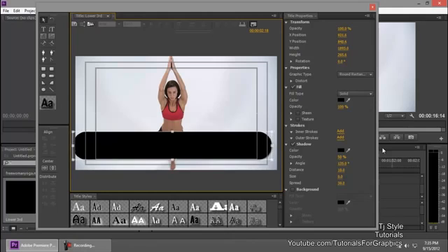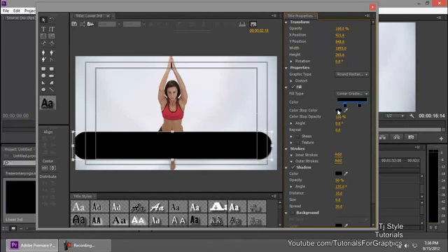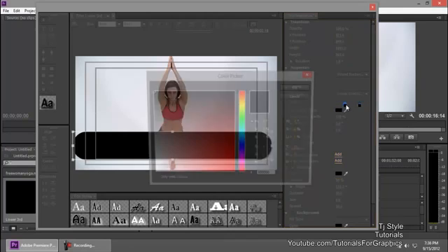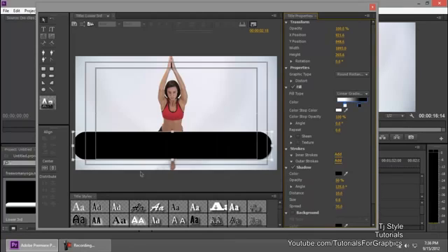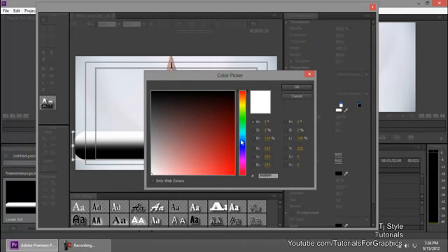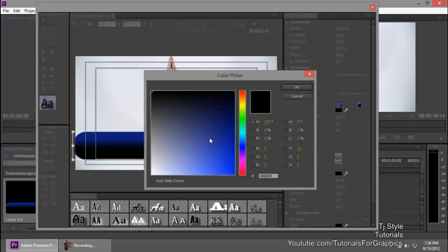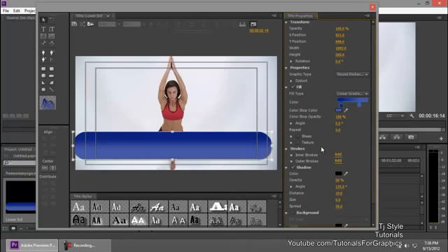And then guys, you of course have the option to change the fill color of this box. In the title properties, go down to this panel, come to Fill Type, and go to Linear Gradient. You can have two options over here now. You can have the color stop opacity, meaning say if I go for a very basic kind of effect with black and white. Actually black and white won't do well. Create a blue one, say like this, and one more blue but a lighter one this time, say like this. Then I could add this kind of a 90-degree angle.